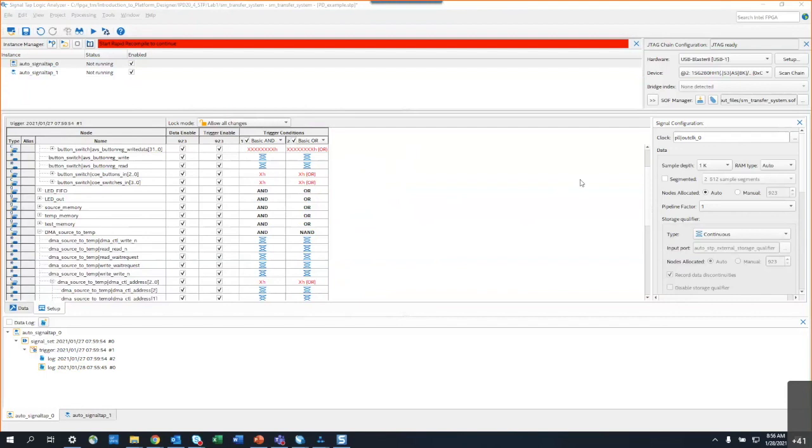And you can trigger a partial reconfiguration at any time while the design is running. The problem with that with SignalTap is that if your design is changing, how does SignalTap work? So you can have SignalTap located in what's called the static region of your design. That's the part of the design that does not change with partial reconfiguration. And there's no issues with that. But you can also have SignalTap in a region of your design called a PR, or partial reconfiguration region, that does change.